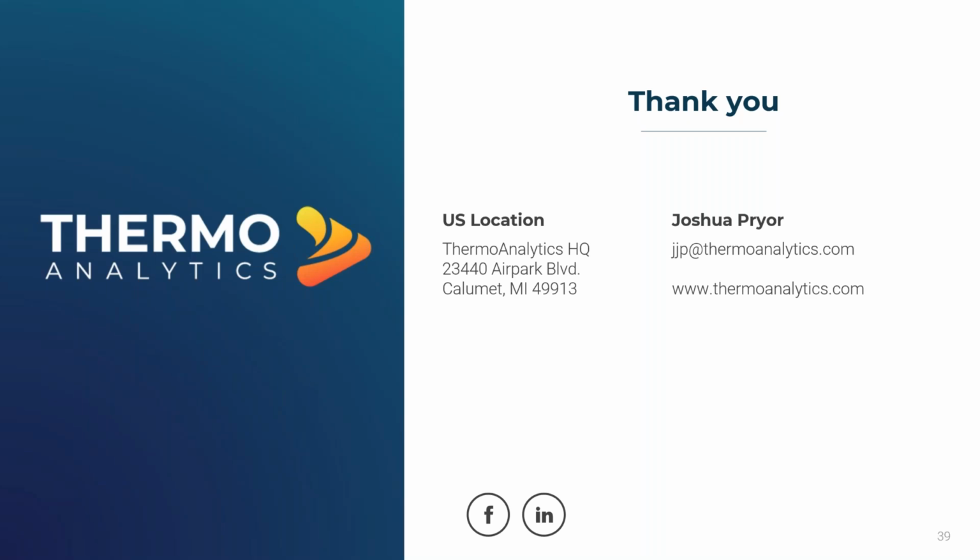And then once we got to the optimization case, we were controlling that. We showed that cost function that was based on the comfort and the energy usage. So we were controlling it based on the human results indirectly. The optimizer tries out a value of that vector, sends it to the surrogate model, which updates the heat transfer coefficient, and then the comfort results end up closing the loop with the optimizer, giving it the feedback to choose the best value.